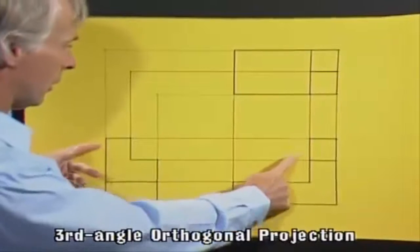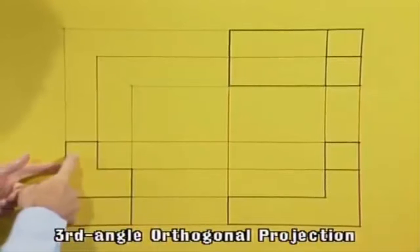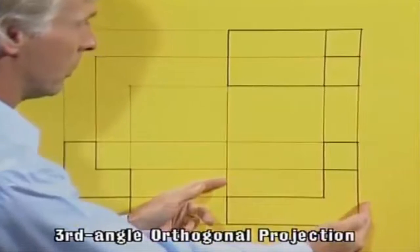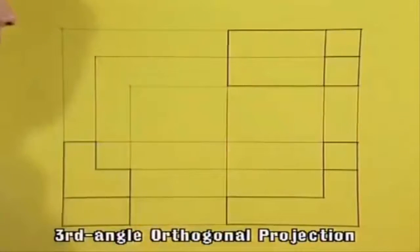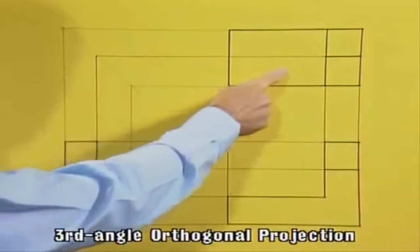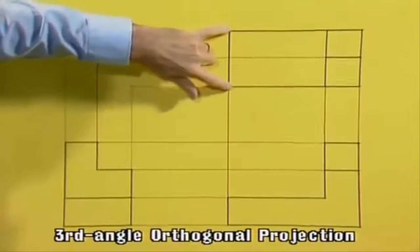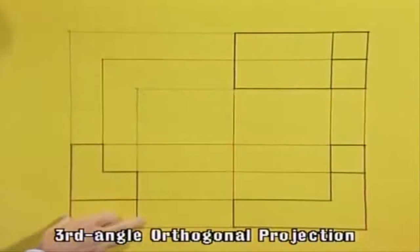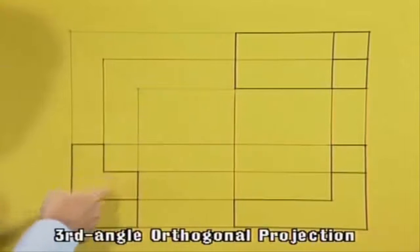As I mentioned before, all the heights from the front elevation are projected across onto the side view, so I only had to measure the width. All the widths of the front elevation were projected up to the top view, so I only had to measure the vertical dimensions. But we can also set up a projection system. That means that the dimensions measured in the vertical direction on the plan view can be transferred straight onto the side view, or vice versa, so we only have to do that measurement once.